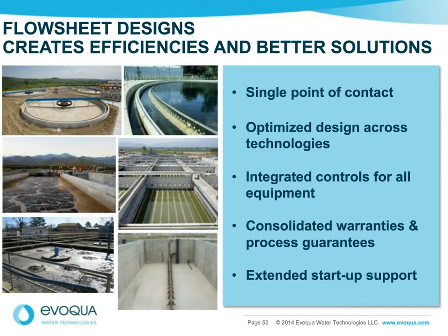Now, obviously, when you look at a biological process, BIOMAG is just one component of it. Because we want to make sure that the overall installation will be effective in operation, we typically will do what's called a flow sheet design. We look at the RAS pumping, the piping sizes, your clarification, your aeration capacity, et cetera, and make sure it's appropriate for the technology of BIOMAG, and that you're going to get a very efficient, very reliable process. So we'll do that engagement either ourselves or with an engineering firm to ensure that the overall process will meet the desired treatment capacity of the system.